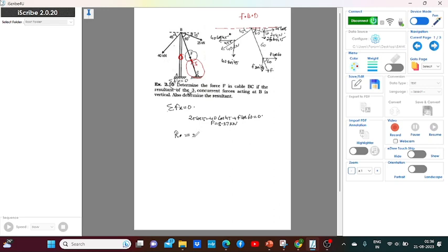So the summation of all the vertical forces is 25 sin 15 in the negative direction, minus 8.27 sin 60, minus 40 sin 45, which is equal to minus 41.92 kilonewton. So it can be written as 41.92 kilonewton in the downward direction.